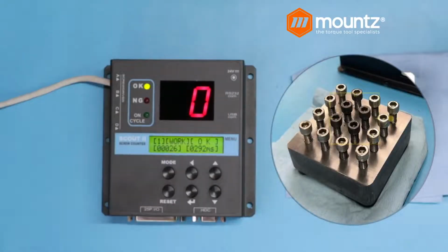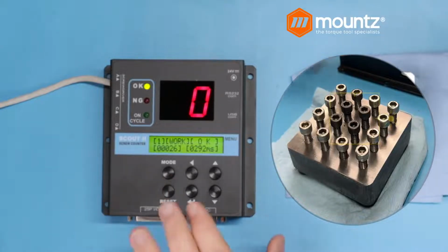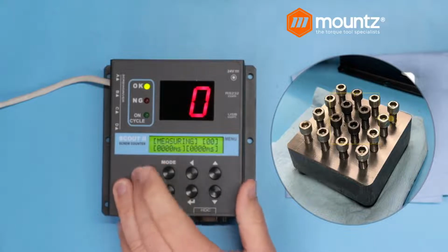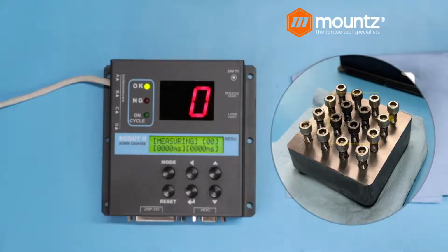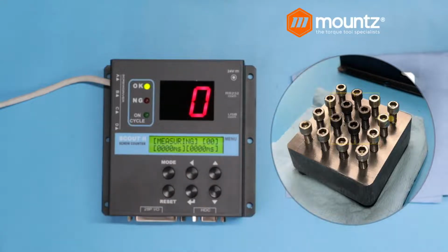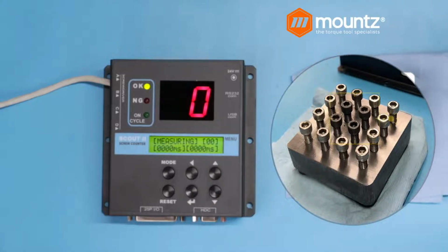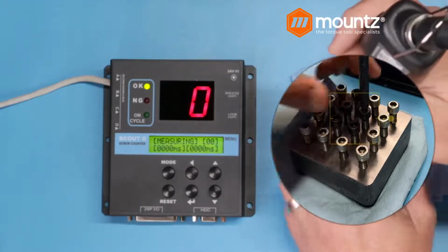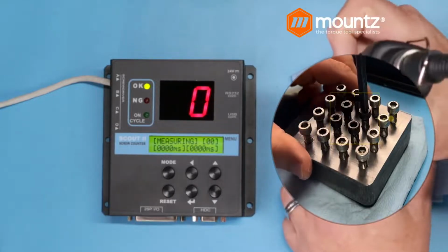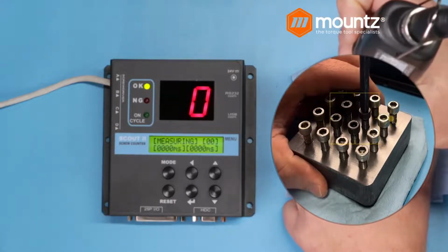So if we have any questions with that, all we need to do is log into the controller, which I've already done, and then we can go to the different mode here, and you can see we're in the measuring mode right now. And so we'll have our minimum time here that it takes, and then our maximum amount of time. So I'll go ahead and run 4 fasteners down, and we'll see the actual values that we get for the rundowns. So let's go ahead and do that.